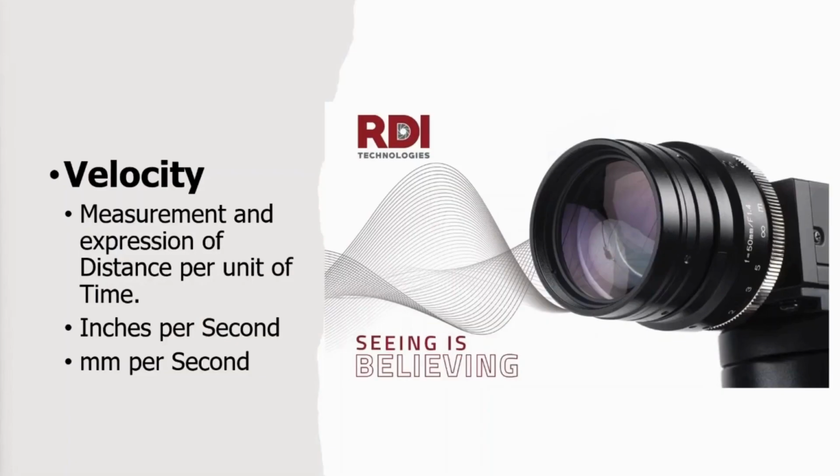Another way we can both measure and express a vibration amplitude is to use velocity. So velocity is a measurement or an expression of distance per unit of time, or maybe in plainer language, speed. And so kind of like speed, where we're used to measuring speed maybe in miles per hour, in the vibration world, velocity is measured and expressed in inches per second, or in the metric system, millimeters per second.